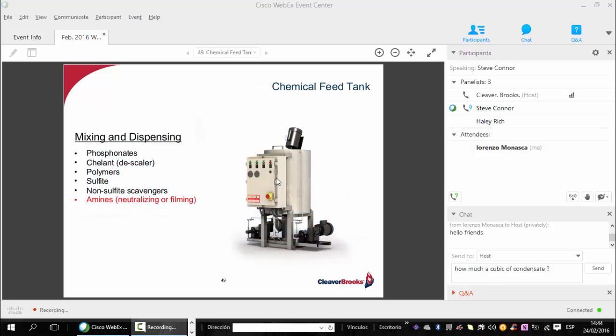And I mentioned the DA eliminates the carbon dioxide from the raw makeup water containing carbonates of alkalinity, which when mixing in the DA water and heated turns to CO2. So this then helps eliminate condensate line corrosion in the form of carbonic acid attack. But the DA will not do the whole job on its own.